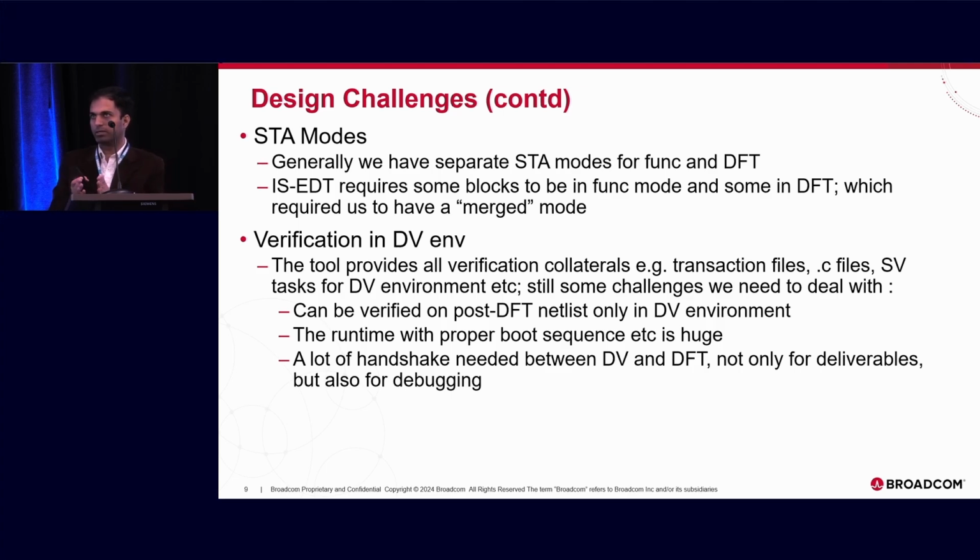I want to mention that the Siemens tool does provide us the test benches to verify it in DFT, but that starts from the IJTAG input, so the IST controller input. From the APB and down through the SSH to the targeted blocks, we can verify everything. But in the whole system environment, like a functional block reading from SRAM and then putting it on the APB, all that has to be done in a verification environment. So the real verification, or the true verification, is done in a functional environment.